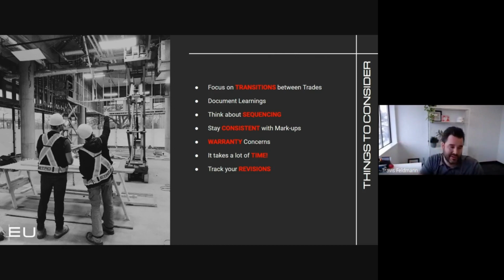Go back and look at your previous work product and make sure that that flashing type at the bottom of the window is scoped out to the curtain wall contractor, or this transition from inside to outside is scoped with the correct trade, so your sequencing flow is similar throughout all your details, and that you haven't swapped trade responsibilities midway through your markup between days.